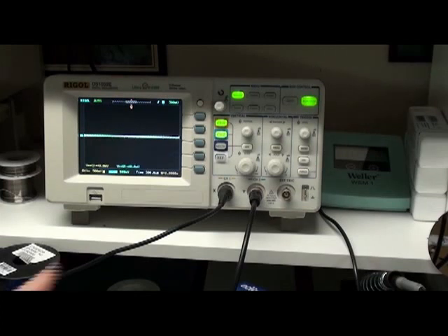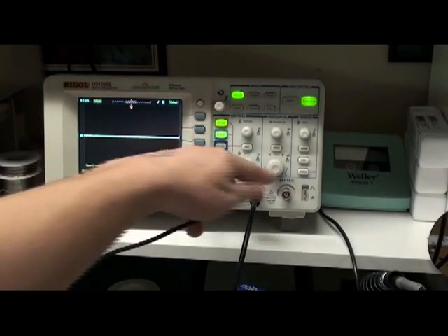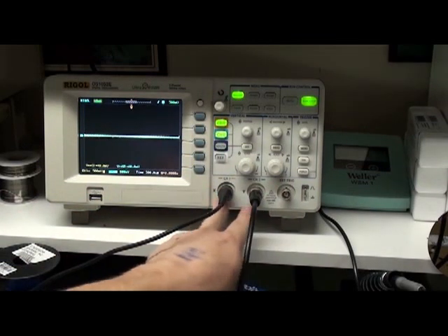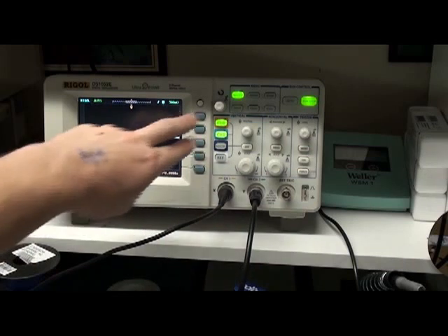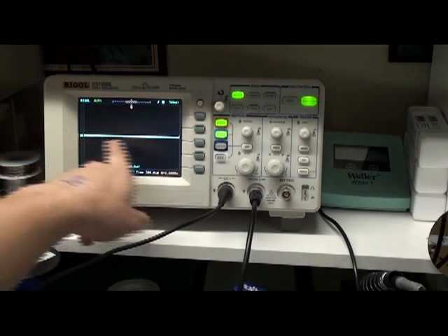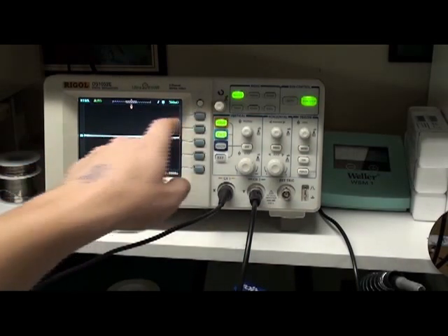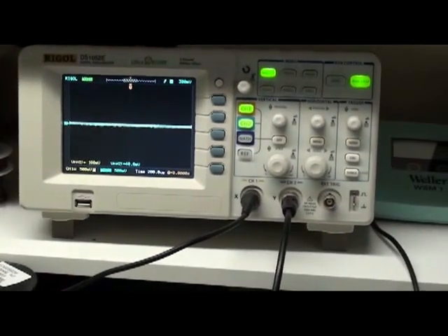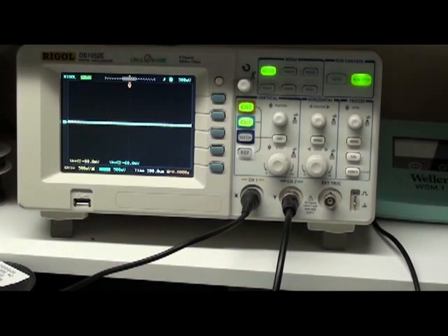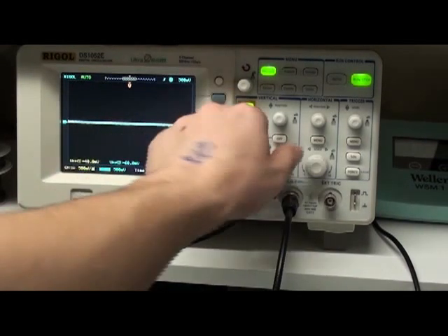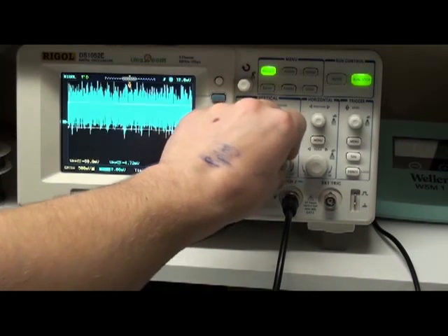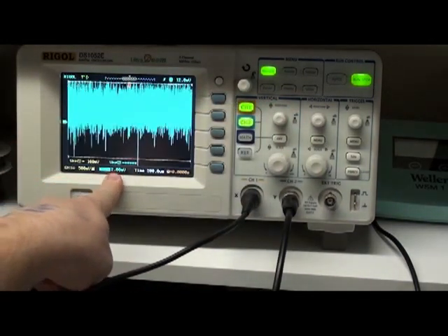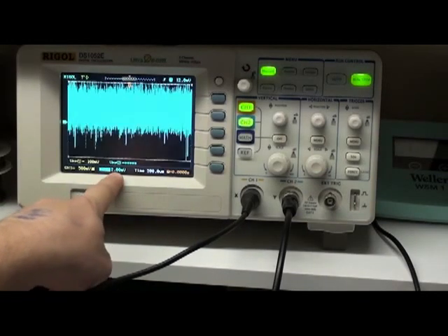Righto, so here's my oscilloscope. It's actually got 2 channels, so this is just like your scope in Simulink, but the real one. They're both on, and they're both being drawn here. Now the reason you can't really see them is not because I haven't zoomed in, even though I will a little bit more, but because there's not actually any voltage across them. Now if we turn this one way up, you'll see that there's heaps of signal, and I'm not sure if you can tell, but this is on a 2 millivolt scale.